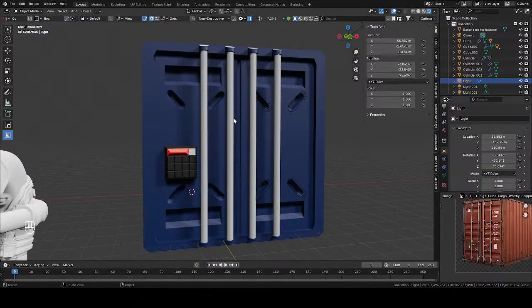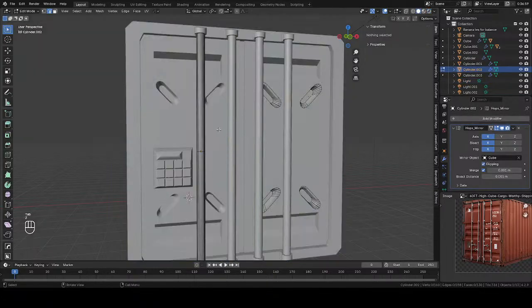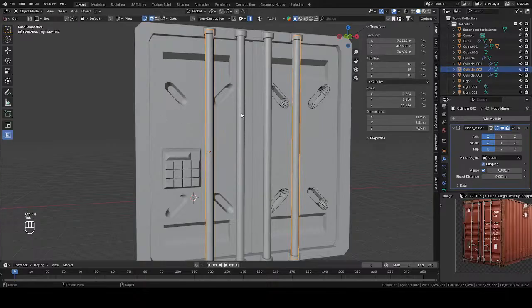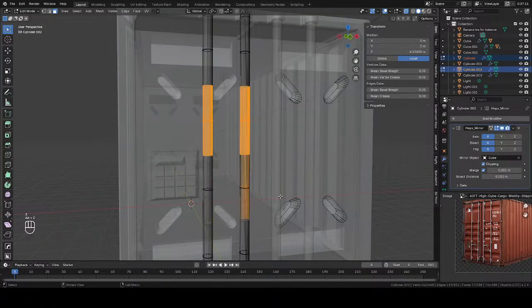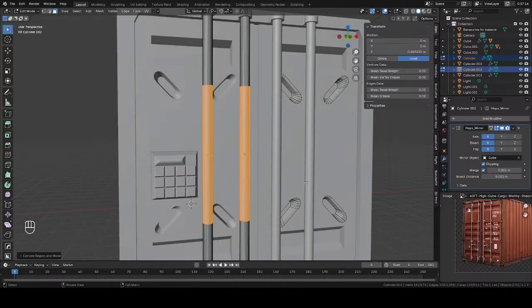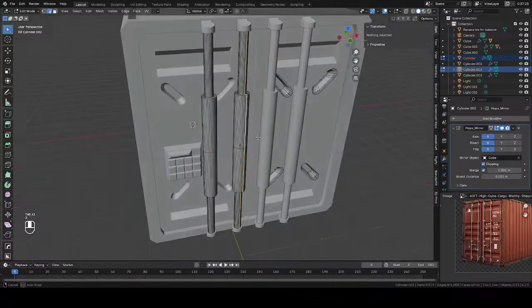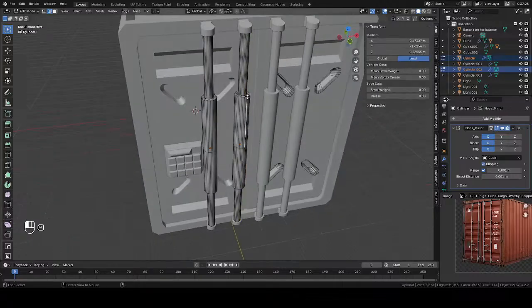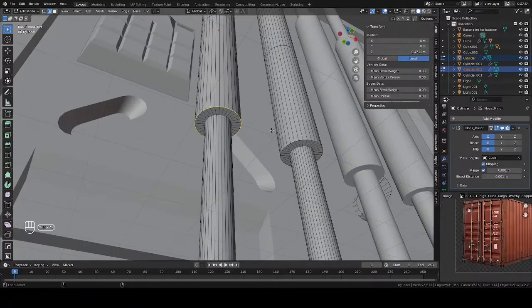So these will disengage. So they have to have some place to kind of go to. Makes sense. I'm just gonna add an edge loop here. I'm just gonna take these faces, then extrude them slightly. Hit E to extrude and then Alt S. Something like that. Take the tops, these top edge loops here, and click on it. And then just bevel these slightly.